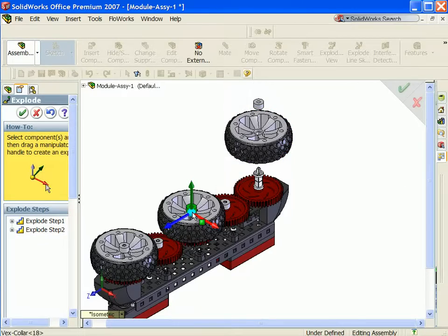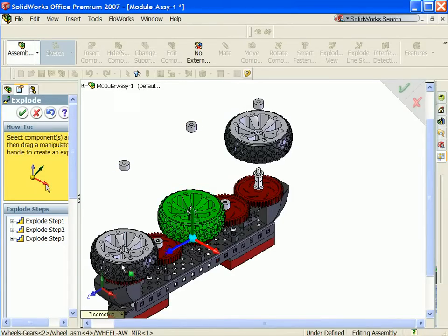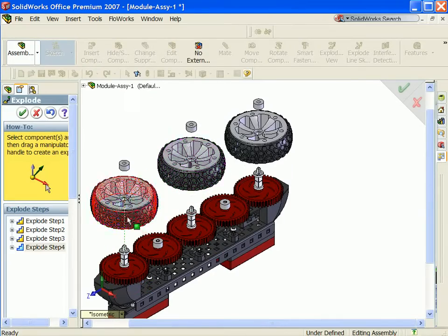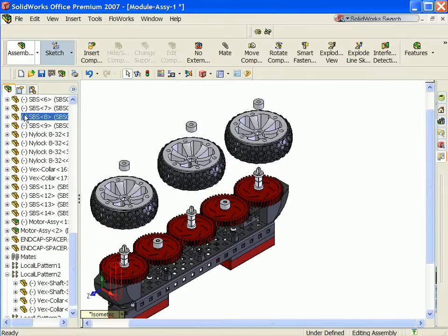You can utilize 2 or more components in the assembly to explode by selecting the Control key first. Notice how I move 2 shaft collars at one time, and then I will move 2 tires and 2 wheels. If I prepare my exploded view as if the components would be assembled in manufacturing, I can see virtually errors